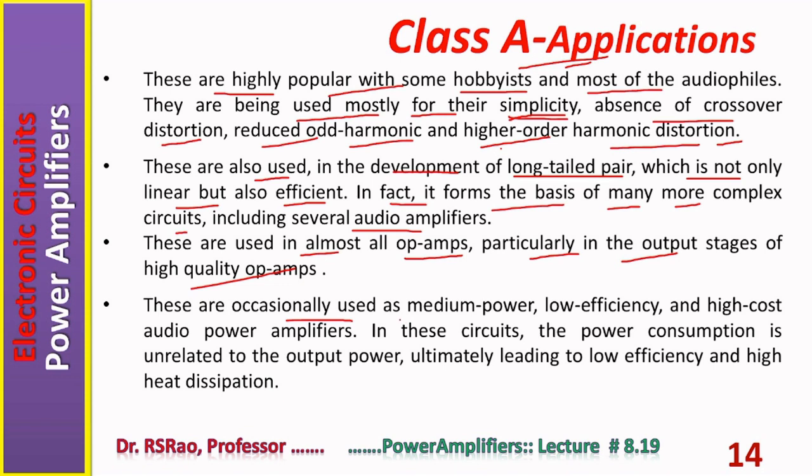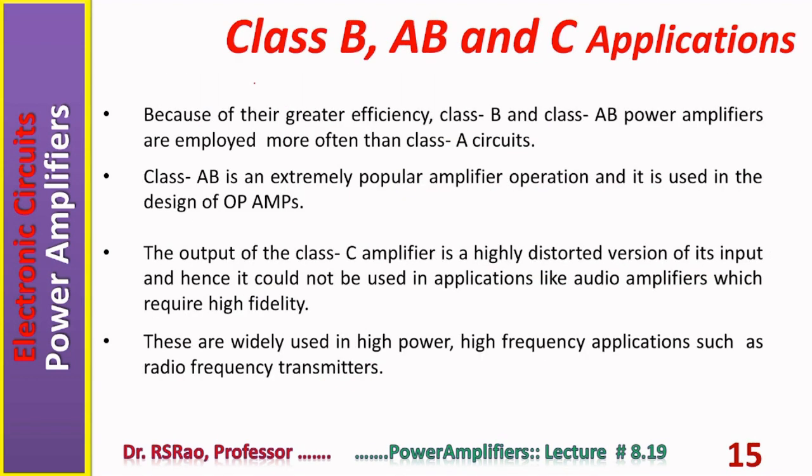These are occasionally used as medium power, low efficiency, high cost audio power amplifiers. In these circuits, the power consumption is unrelated to output power, ultimately leading to low efficiency and high heat dissipation. Now, class B, AB, C application.